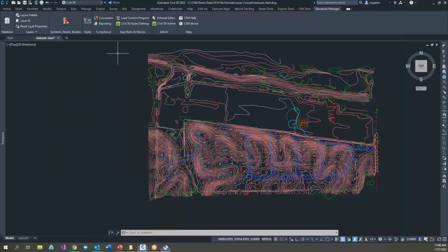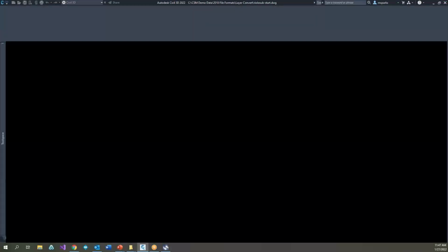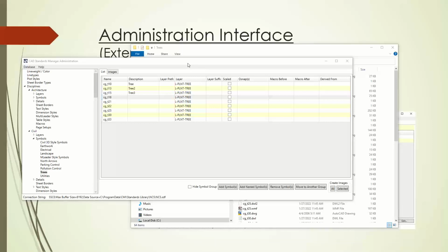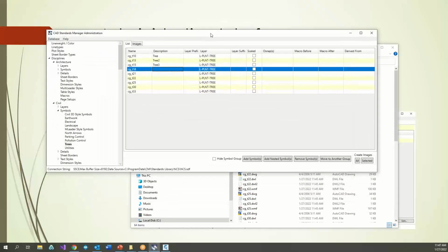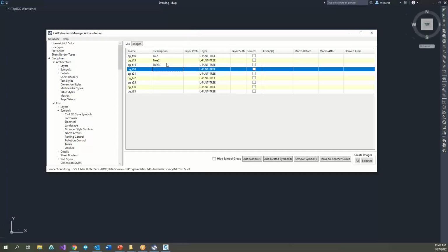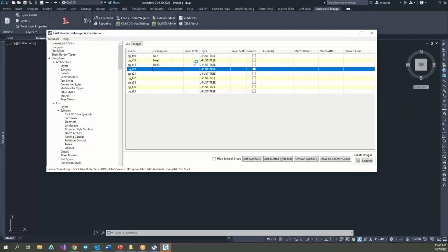So as I do this, I'm making this change. So the next time that I open up CAD, which I'm going to do now, just to show you one time here, I'll go back and open up Civil 3D again. It's opening now. It's just taking a second. There it is. So I should have a new symbol group for trees and have all my trees in there, etc. When I insert one, it should go on the layer L plant tree.